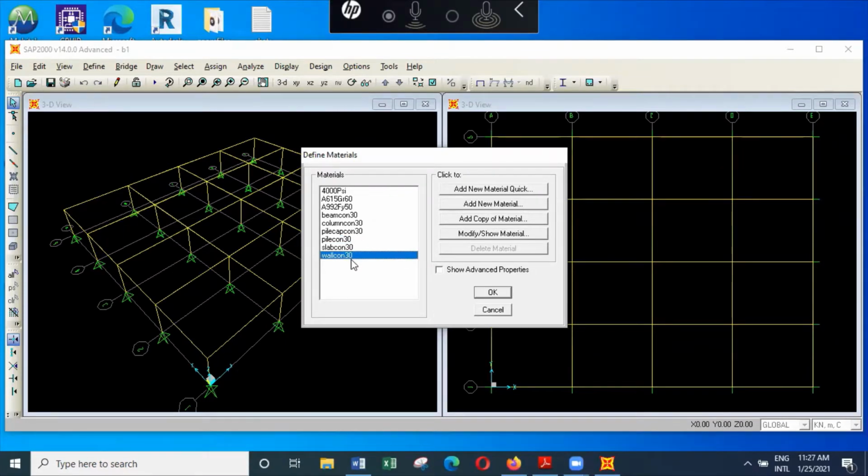And the way that I have modeled is, I'm not going to model the slabs for load transfer. And what I'm going to do is, I will consider unit load acting on the slab, and then allocate the load transferred onto the beams using a unit load. So I'll come to that in a moment. But before that, you can first see that I have defined different materials for all the different types.